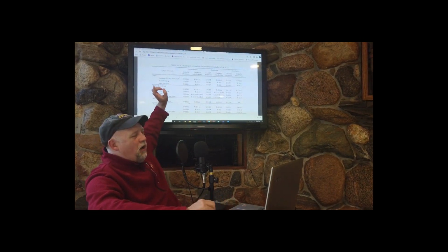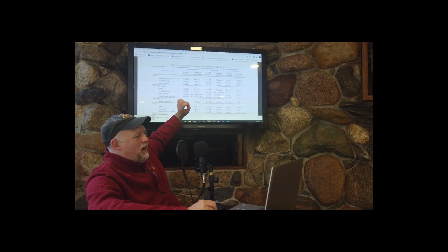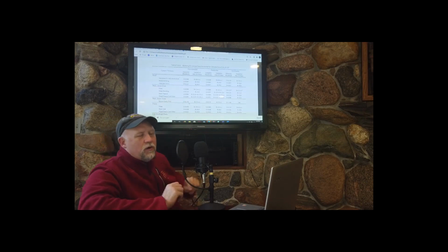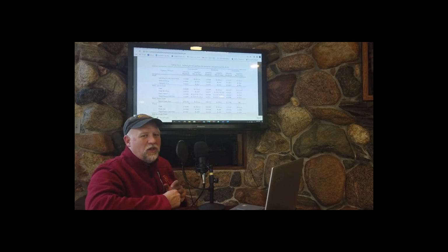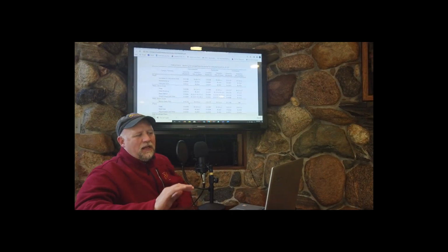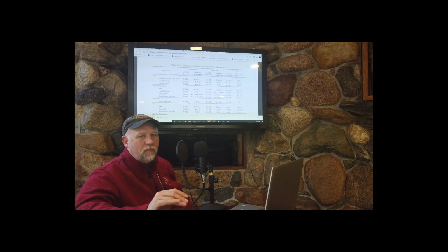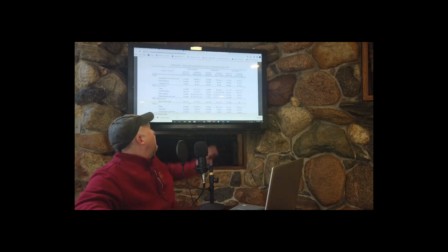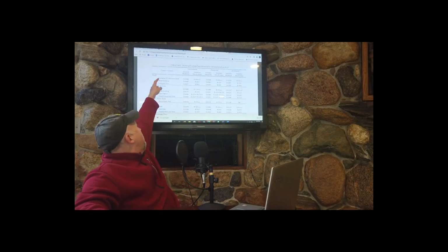So depending on what type of structure that you have, whether this is insulation entirely above deck, that's going to be most of them. If we're talking about a commercial or educational building that has a low sloped roof, and we have the structure, and then above that structure is the insulation, which is, like I said, the vast majority, you're probably going to be using this value.